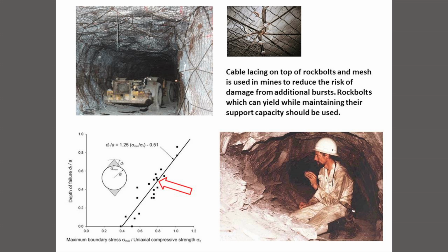So we move on a little bit deeper underground now, and we get higher stresses, and now we're getting pretty serious failure of, let's say, the whole tunnel sidewall, as you can see in the bottom right-hand photograph. And this is much more difficult to deal with. In mining, where you are dealing with irregular openings, and the stresses are constantly being changed by mining adjacent areas, you have to try and prevent this rock from failing further.